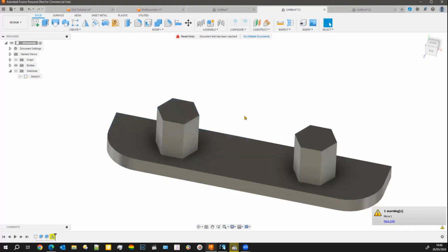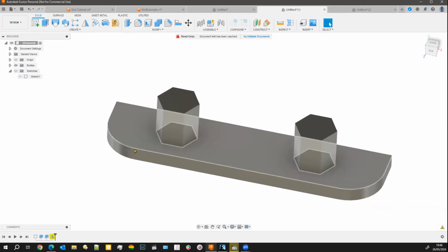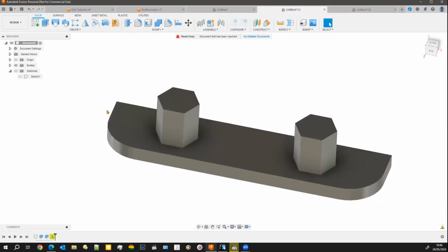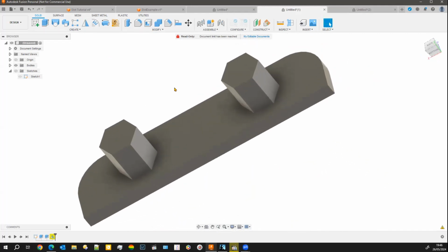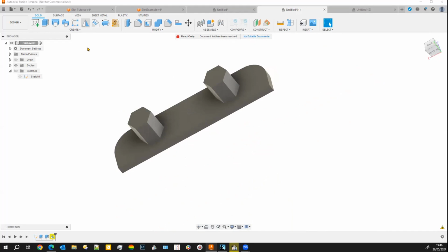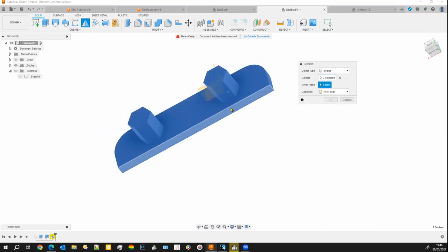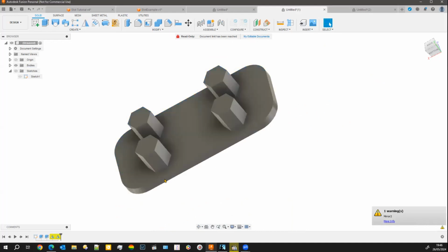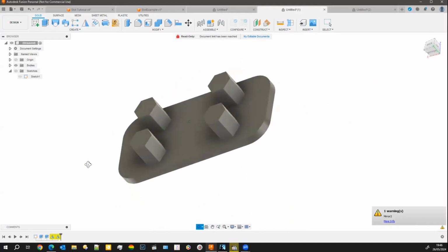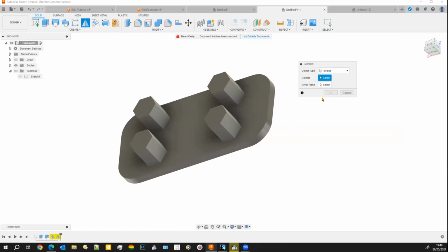Now this is handy if you're doing, say, wagons. So you've created one side of a wagon. Or as I did with the roof of the rail coach, I developed one quadrant, as it were, because now of course we can turn that round. We can go back into the mirror command, highlight it again and select that plane, and you can see how we've quickly produced something of that nature. Go into mirror, you can see there's no options at all.